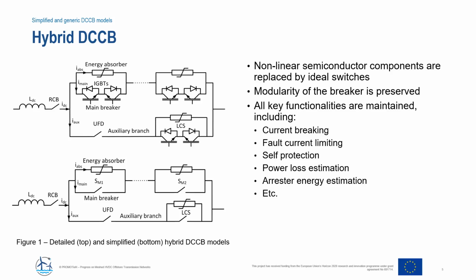On the other hand, the modularity of the breaker model is preserved and all key functionalities are maintained. These include current breaking, fault current limiting, breaker self-protection, power loss estimation, arrestor energy estimation, and so on.